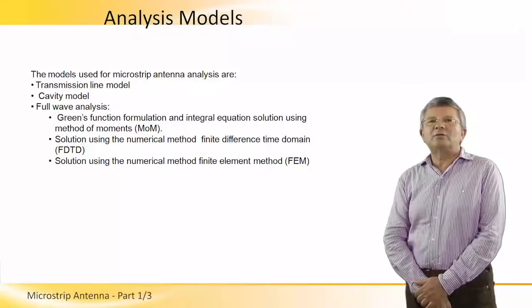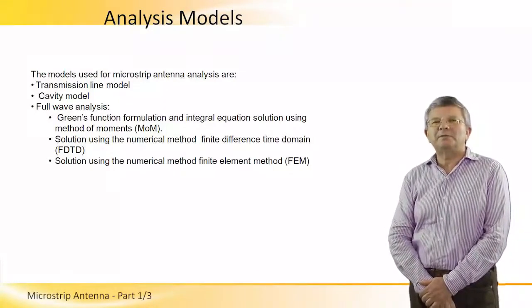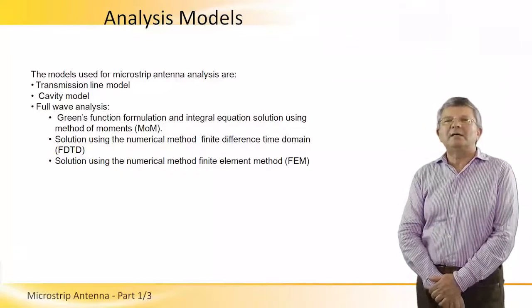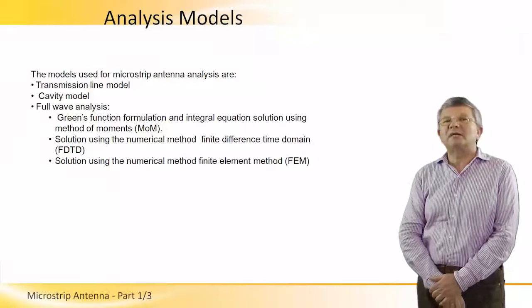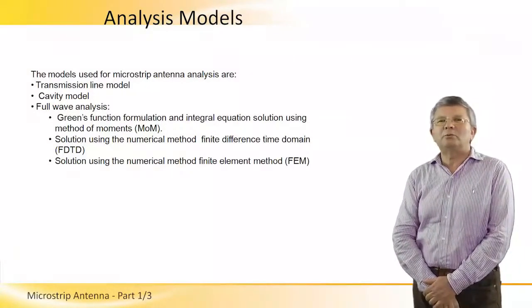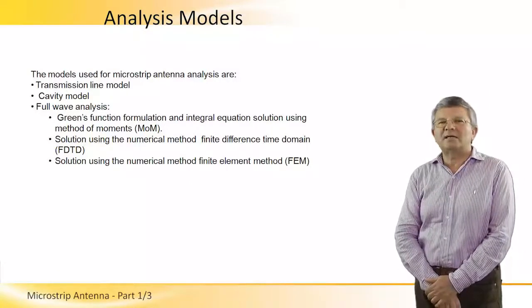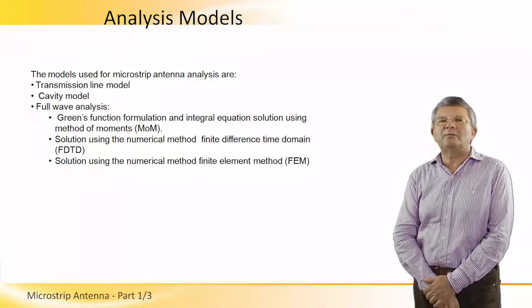However, of course, the full wave analysis is much more complicated to implement, and in simple cases, we may use the transmission line model and the cavity model because they give some sort of insight into the problem, which helps the designer before he gets into the more complicated type of analysis.